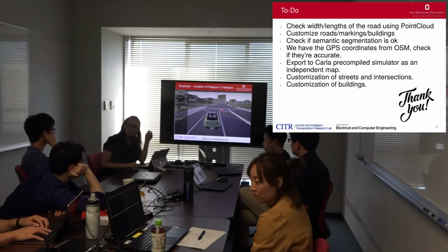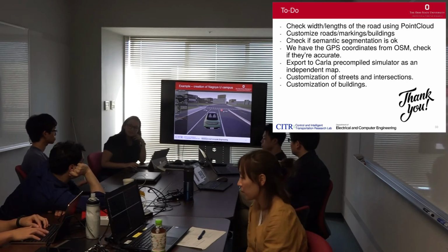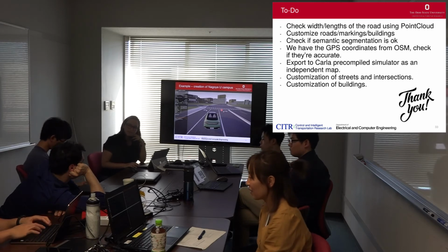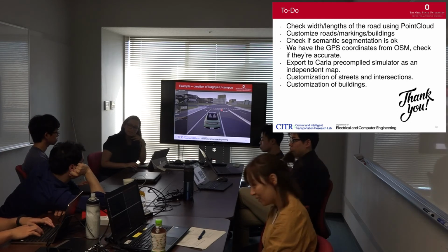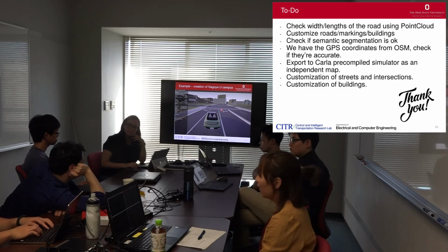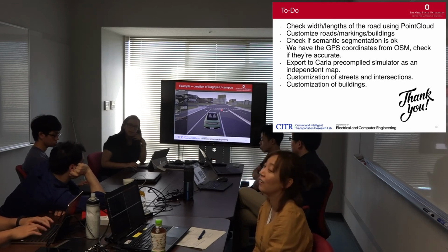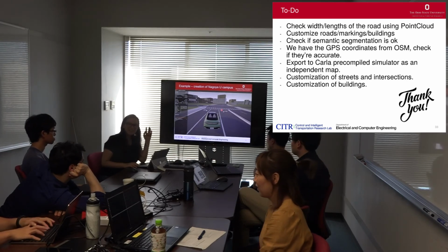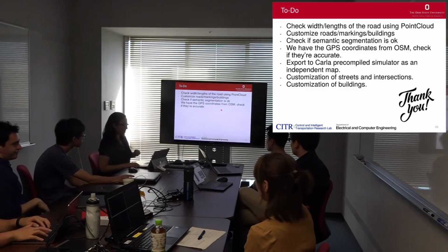Yeah, what I did is I got 3 points with a really expensive GPS device, and I recalculated the points in the OSM map according to that, got the error, and then applied the error to all the points. I think maybe we could implement this here, for actual use. Yeah, it's still doable. Not so bad, I think.